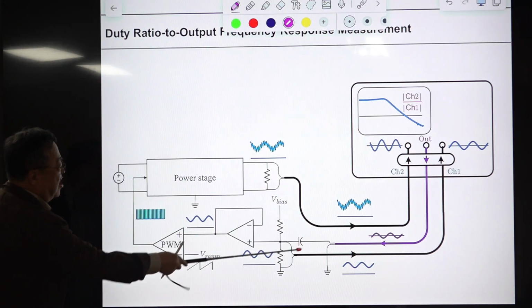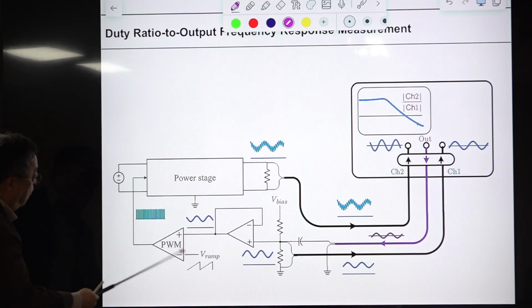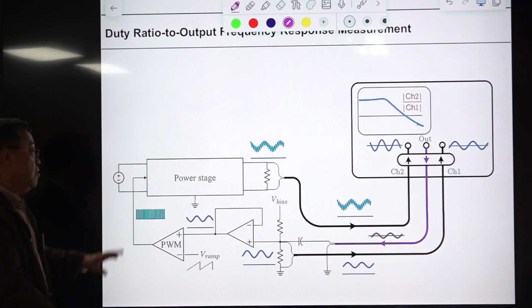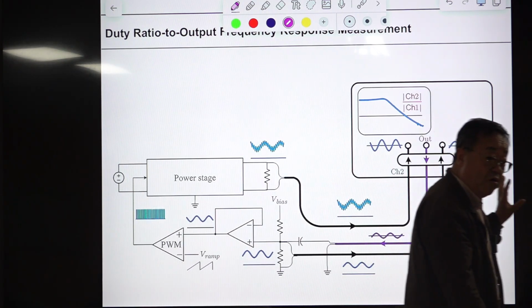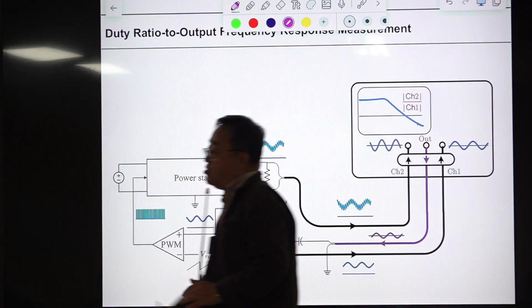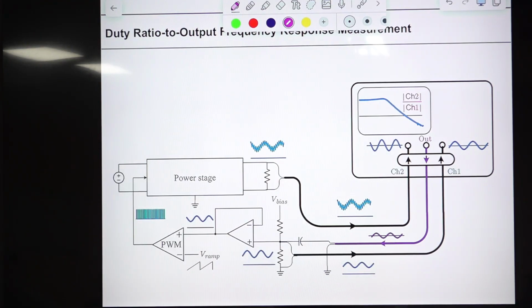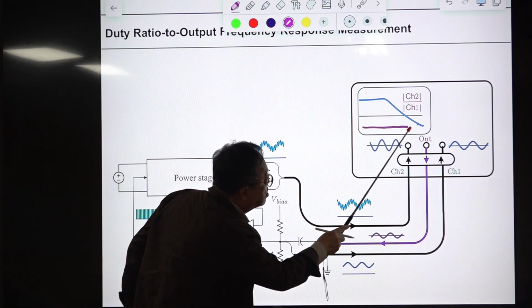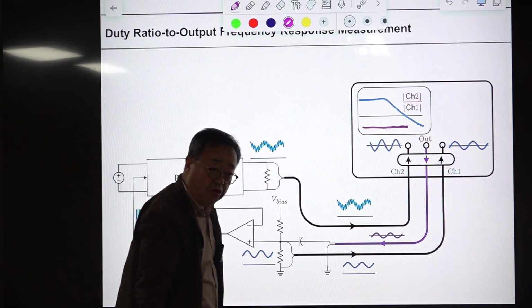So this is injecting the sinusoidal waveform, and this performs the duty ratio modulation, and this is our voltage. And for that, we are using this impedance analyzer I previously introduced. Okay, there are 3 terminals. This output is injecting the sinusoidal waveforms. You can adjust the magnitude and the frequency, and usually you specify the frequency band. You're not adjusting any knob, you just specify this band. Then it starts from this low frequency, 10 Hertz, 11 Hertz, it goes to 100 kilohertz gradually.